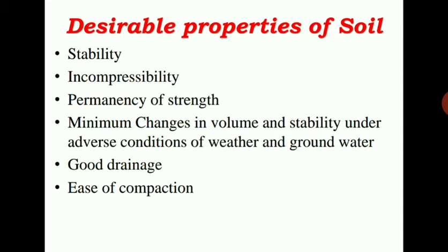That is, if a moist mass of these materials is subjected to compression, they suffer no significant volume change. When soils such as gravels, sands and silts react with the moisture content of the earth, there will not be much change in their original volume. But the other classifications of soil such as clays and others, when they react with the moisture content of the earth, there will be a change in their volume.